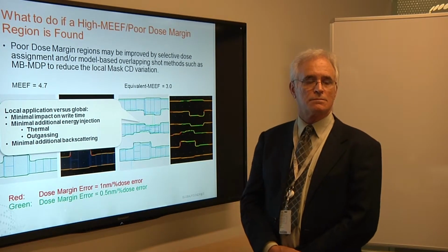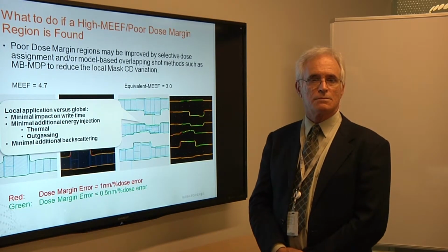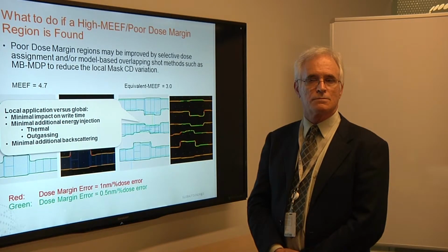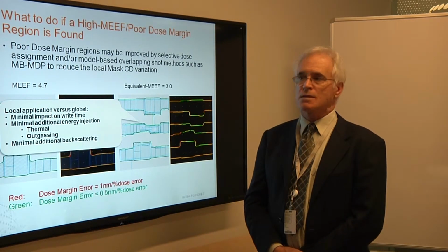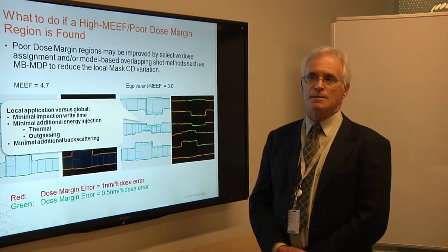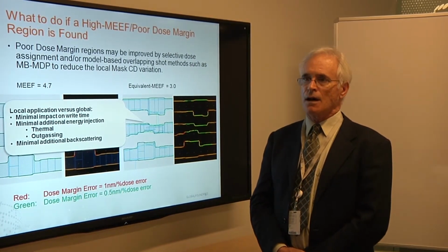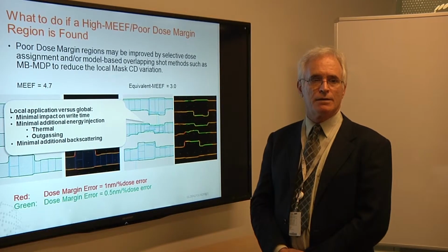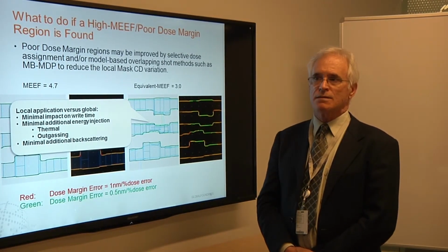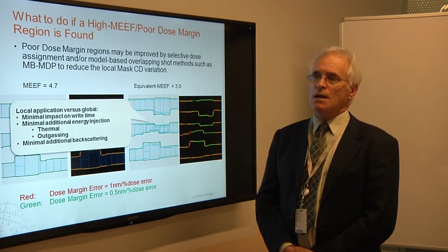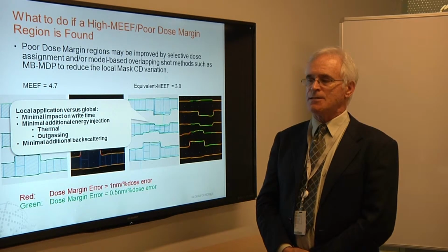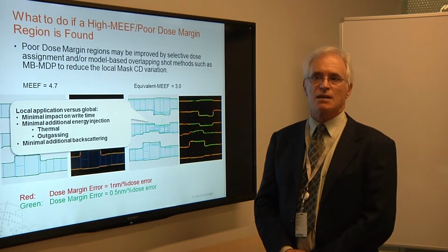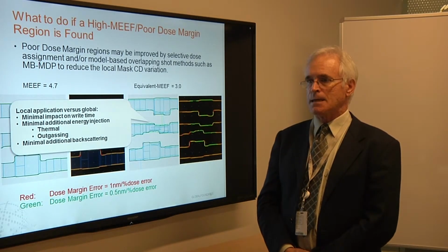Where are we seeing the biggest problem as we're heading to the 14 nanometer mask, 10, 7? Well, certainly you must consider the mask and the lithography in an integrated manner. The problems only get worse. The mask variability is generally considered that you must do mask process correction.